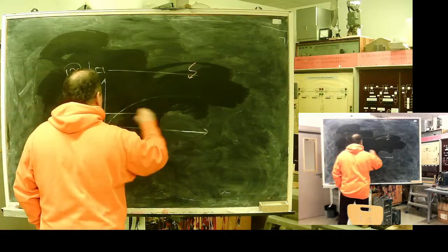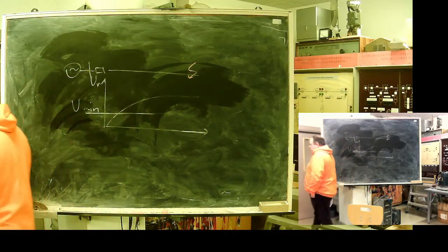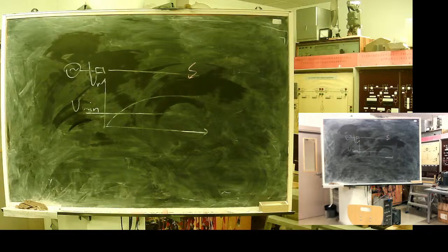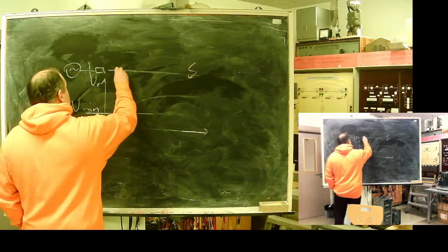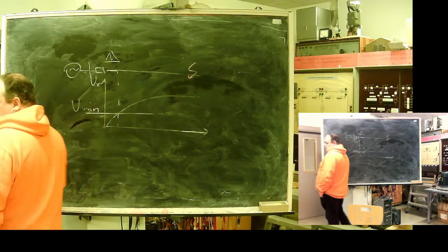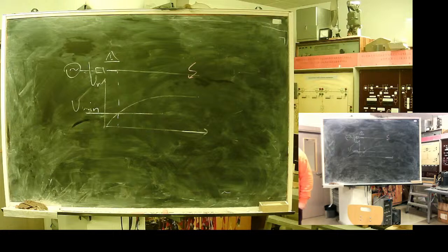We always will have some minimum voltage, a lower threshold where relay logic can calculate resistance, a limit of precision. This means that at the beginning of the line we will have a so-called blind, non-sensitive zone. We need to do something with it.